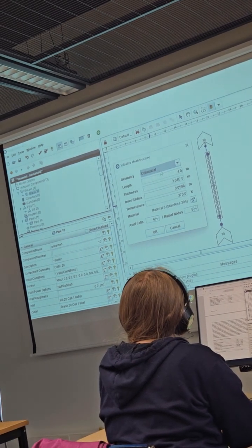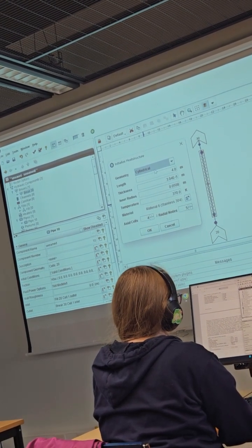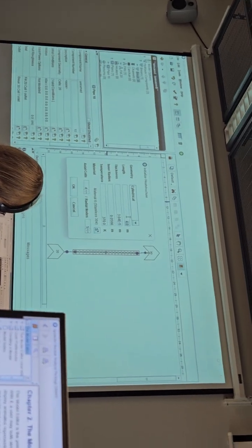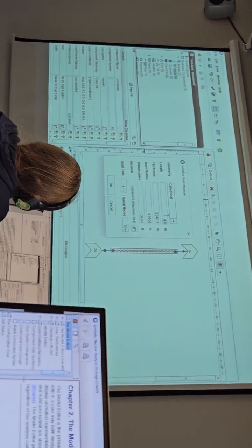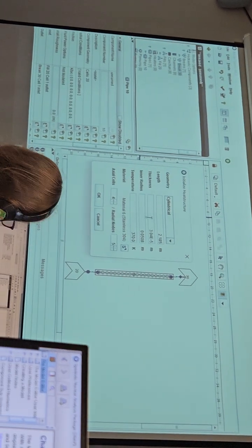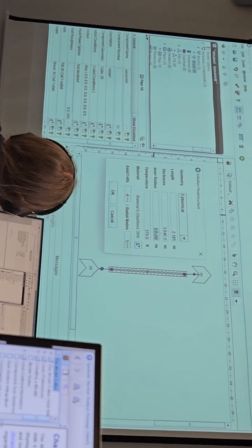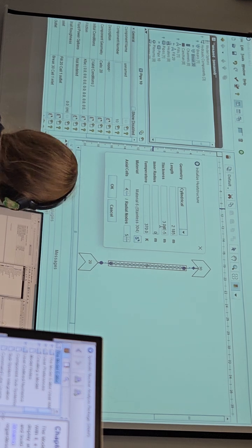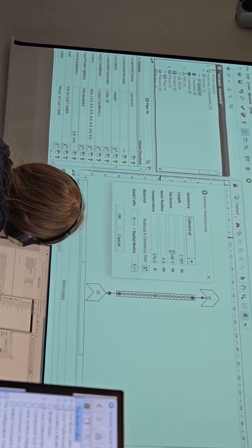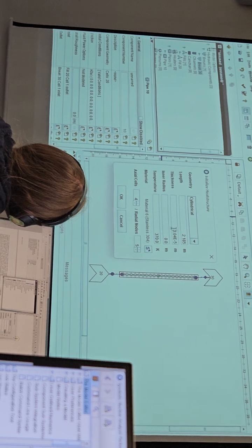For this case, we have a cylindrical heat structure. So we have a fuel rod simulation. The length of this heat structure should be exactly the same as the last pipe, which is 2.185, if I'm correct. Inner radius is equal to 0, since we have a fuel rod. We don't have any inner flow path.